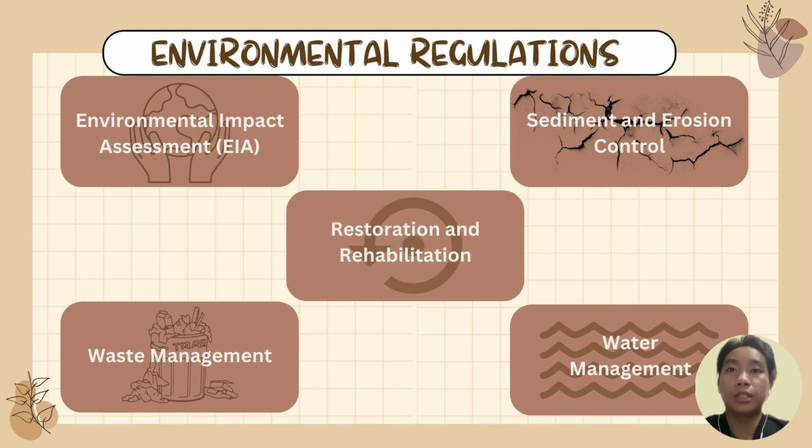It is possible to successfully manage sediment and stop its migration into water bodies by putting best management practices to use. Meanwhile, to avoid excessive erosion, floods, and pollution of surrounding water bodies, proper stormwater management measures should be used. Thirdly, water management. Dewatering operations must be managed whenever there is excess groundwater during excavation works to reduce any negative effects on the environment, including monitoring and regulating flow rates and discharge quality.